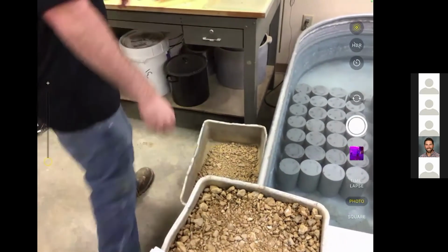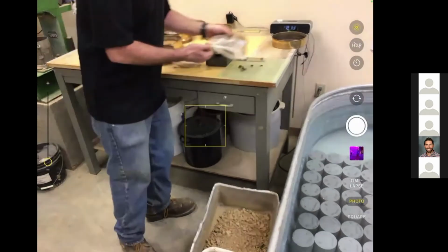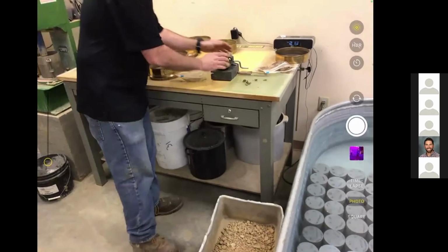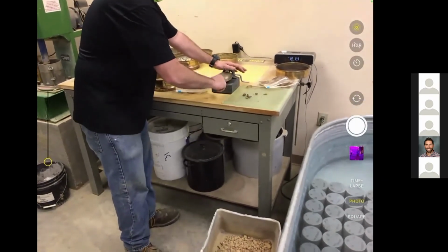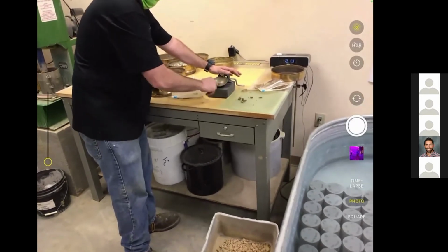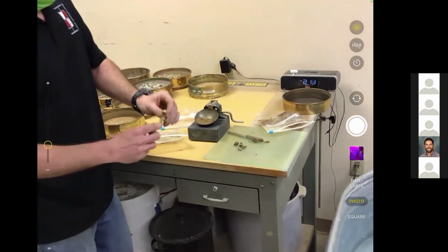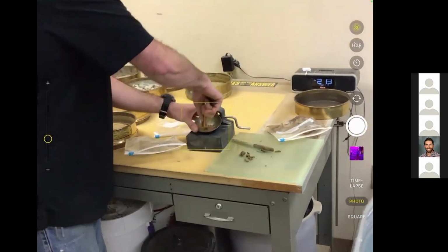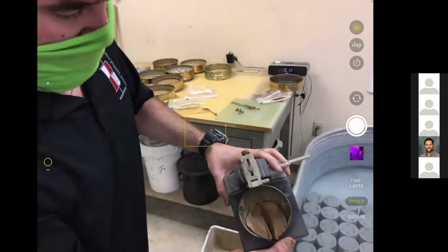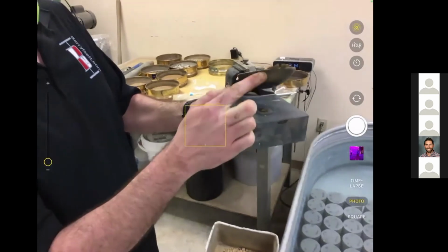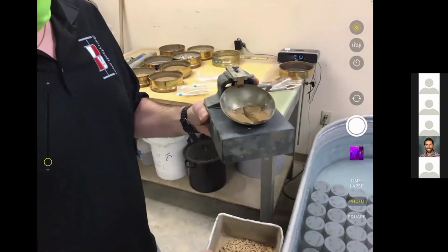The second step is the liquid limit, like we talked about. Basically what you would do, hit it in the bottom, take a knife, spread it out smooth. Take a grooving tool through the deepest part of this cup. Cut a groove. Once that groove's cut, this cup is going to lift and drop at a set height to ensure that everything's following the proper ASTM.